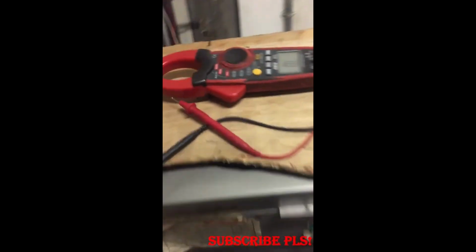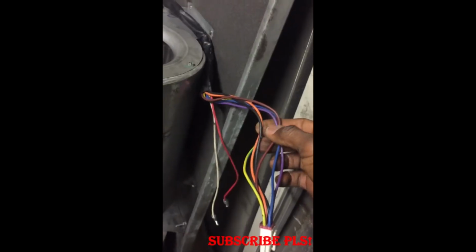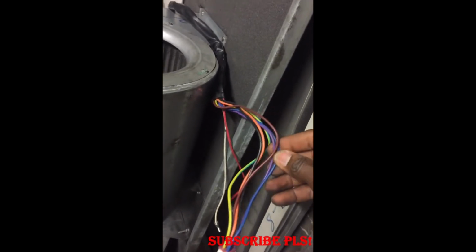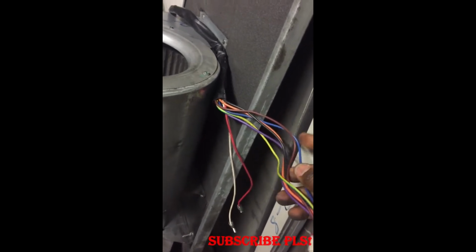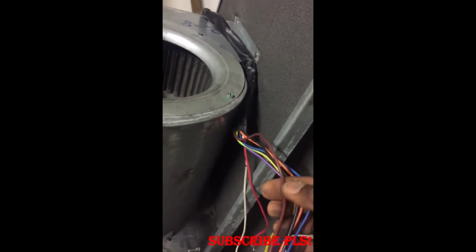As you can see, this cable comes from the motor. This cable comes from the motor. And identify the various cables for the speed control and for supply of power via a capacitor. Now when you get something like this, all you need to do is wire two of them. One of them is neutral, which is this, and then this is the earth. In this particular case, the brown is useless, but it's also part of the speed cable.